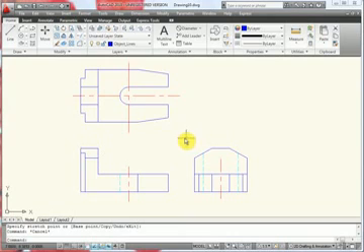three-dimensional part. So you generally would start with a top view of it and then rotate it 90 degrees down and give yourself a front view, and then rotate 90 degrees to the side and give yourself a side view. To aid in connecting geometry from one view to another, use hidden lines. For example, this hidden line right here represents the back of this arc, and these hidden lines represent these lines in the back here, which means really this view is looking from this direction, and this view generally is from this side.